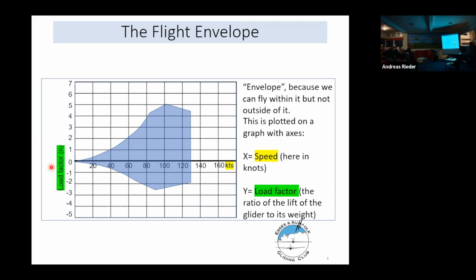When we're talking about these flight envelopes, we're describing a flight envelope for one specific configuration of the aircraft. So this will be with ailerons in neutral, with the rudder in the center, with the elevator in neutral. We're not allowing for, you know, any changes. If you put the wheel down or if you change the flap setting, you would get a different shaped flight envelope. So it's important to remember that every time we draw one of these diagrams, it's for a very specific configuration of the aircraft.